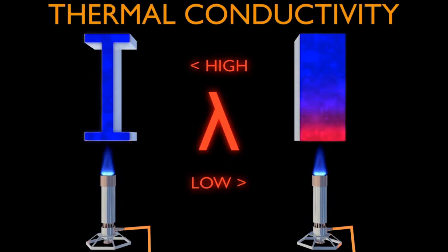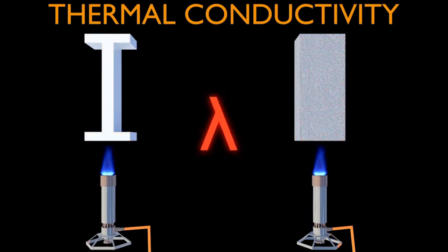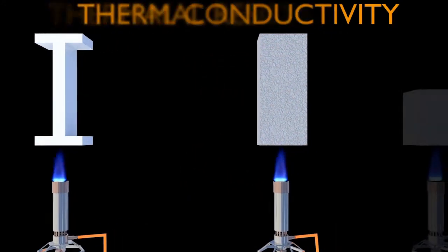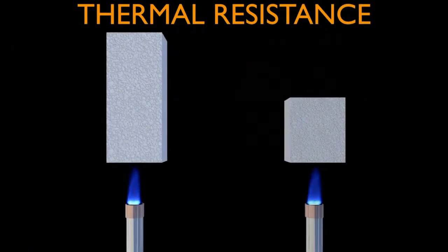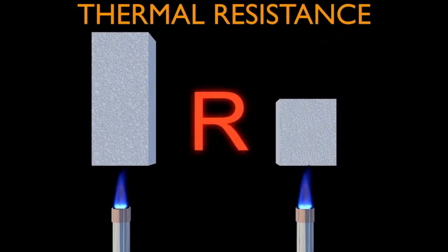Thermal conductivity is useful for comparing materials as it does not account for thickness, making a straight comparison of how good the insulation is easier. It's less useful, however, when we need to consider a specific application, such as a roof or wall, as it doesn't account for how much material we're using.